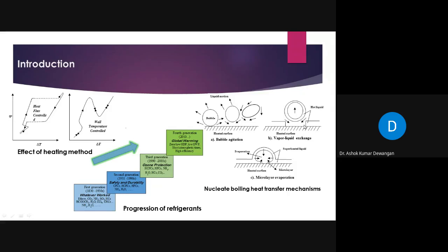The superheated liquid layer is removed from the boiling surface, or heating surface, due to the formation of these wakes, which creates a cyclic thermal boundary layer. But in this case, the sensible heat is transported away in the form of superheated liquid, which depends upon the layer thickness, average temperature, the area of the boundary layer that is removed by the departing bubble, and the bubble departure frequency and nucleation site density.